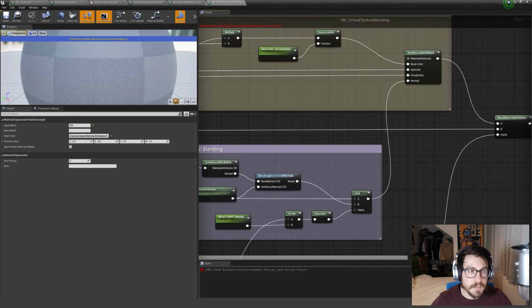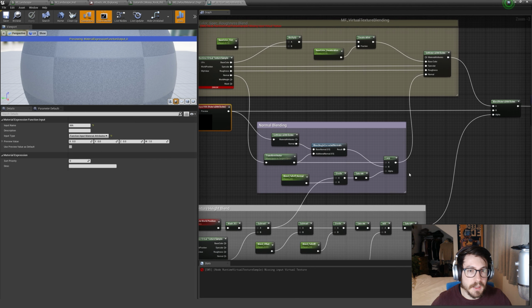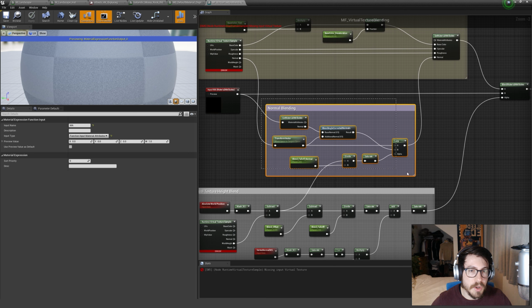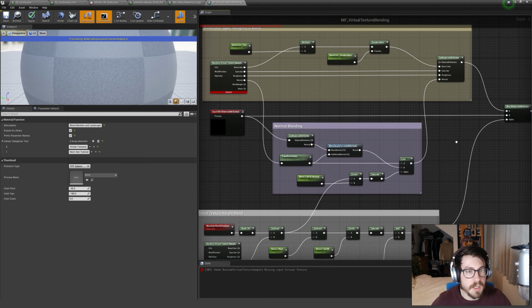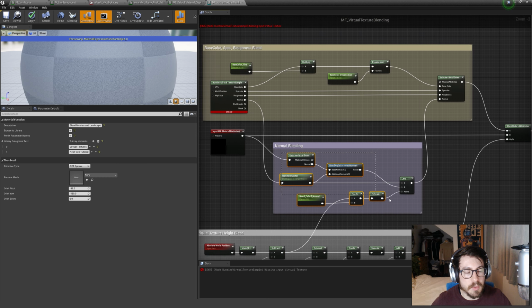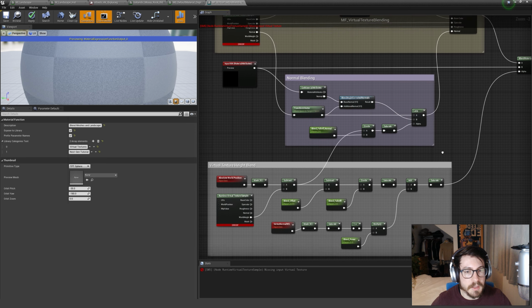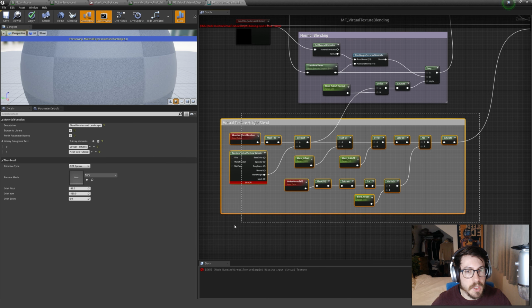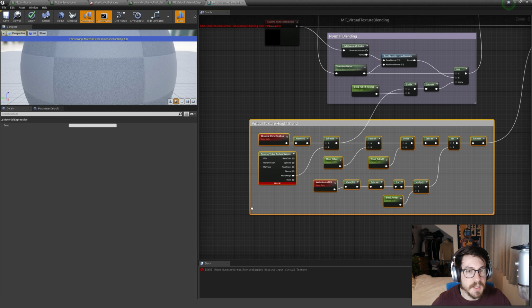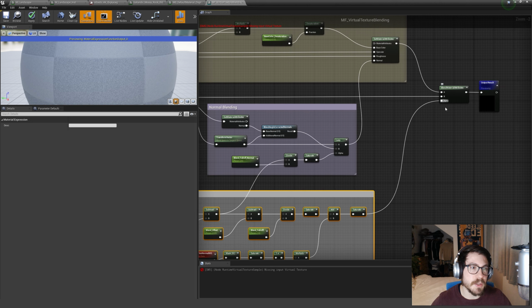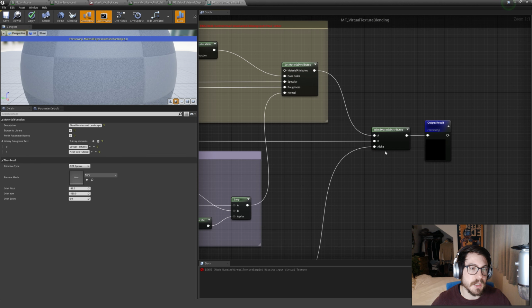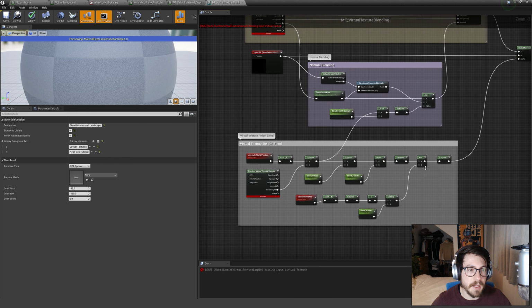And the basic blending, I'm doing a blending for the normal map a bit separately, because I want to blend onto the landscape normals in a certain way. But the default blending is this stuff down here, which is our mask that we use to blend. So the mask is usually piped here in this blend material attributes, right? In the alpha is a black and white mask.